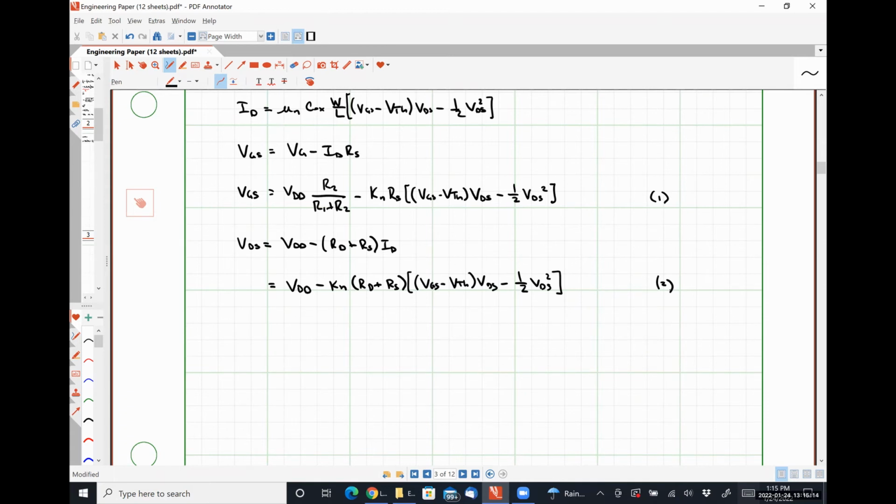You repeat that? What did you say? How much lower? VTH. Or like what should be lower? VDS should be at least VTH lower than your guess value for VGS, because triode region of operation says that VDS needs to be less than VGS minus VTH. Okay. So typically speaking, I would say VGS is 1, VDS is 0, and for the overwhelming majority of NMOS transistors where VTH is less than 1 volt, that's good enough to get the answer correct.